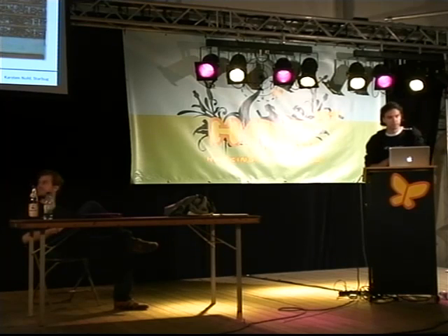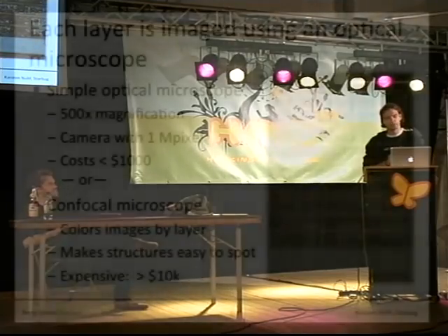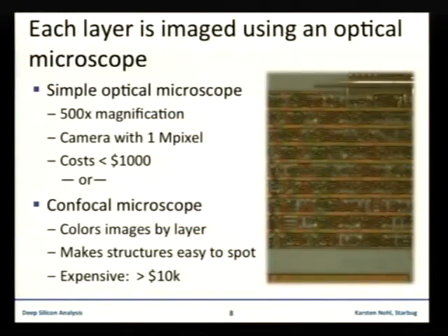After the polishing or etching, you have to make pictures of the chips. At the structural width we are actually working on, we can still use optical microscopes, with magnification between 500 and 2000. It's what we are using right now.